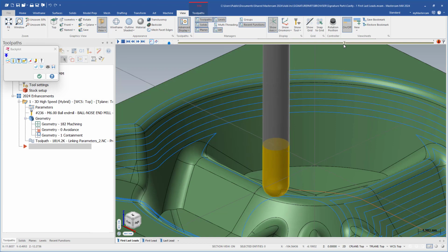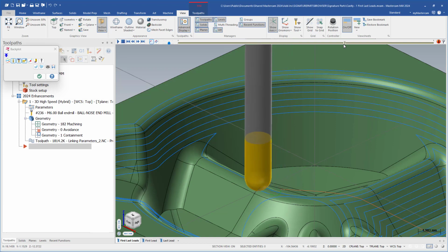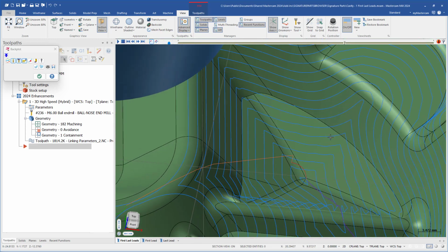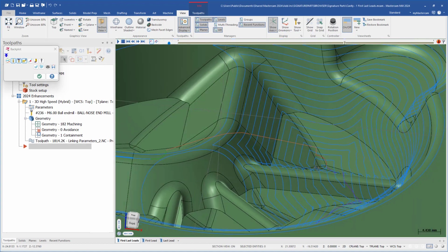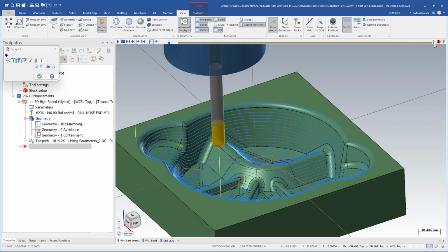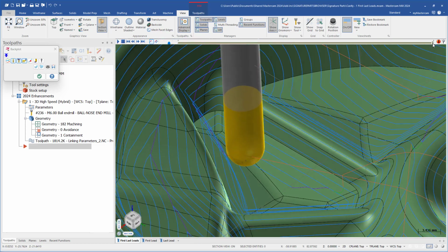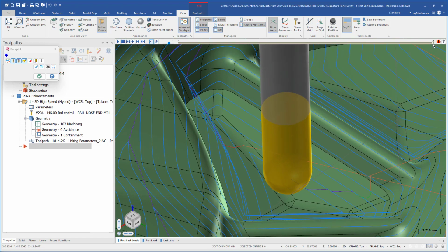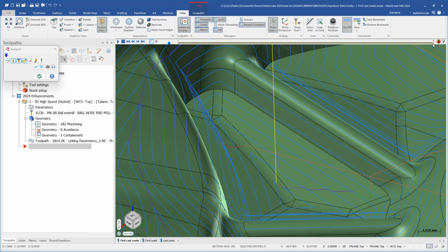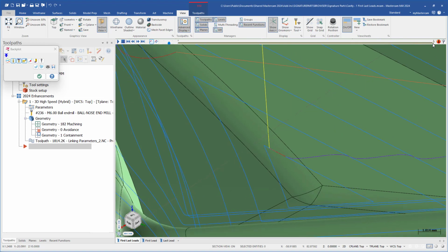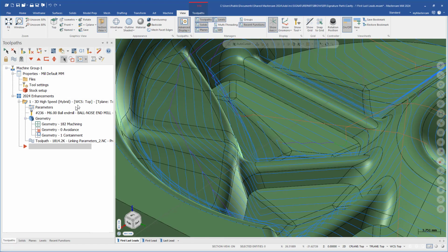This vertical arc, I actually kind of like the vertical arc here. I think that's nice. And for most of this part, I really do want that vertical, just not at the beginning. Also, at the ends of the toolpaths, horizontal works really well, but not for the very last exit. If we take a look here, because of the limitations that we have with this particular area, a horizontal exit really doesn't do very well for us. It basically just flattens out and does nothing. So that's not ideal. So that's where first and last leads come into play.